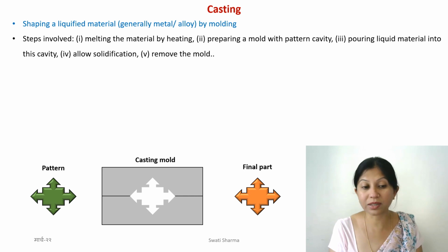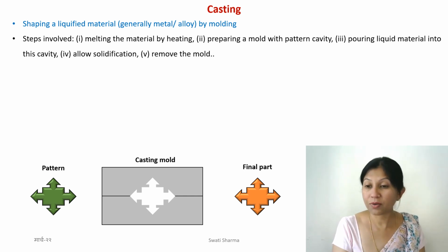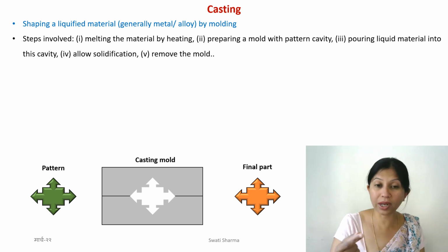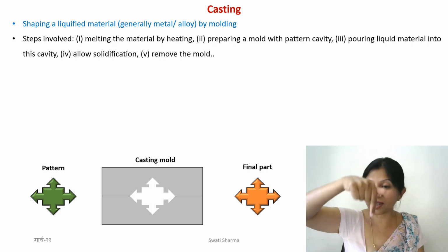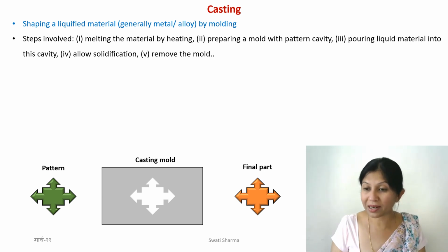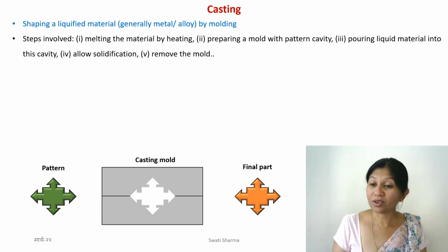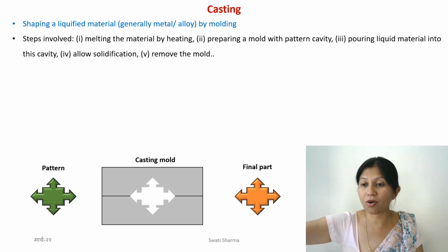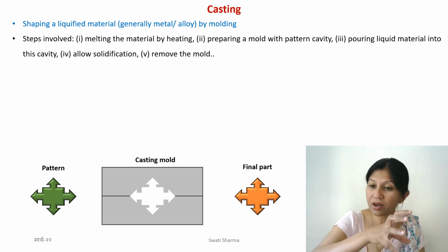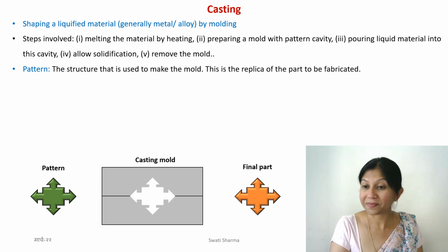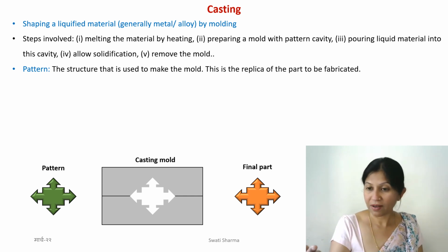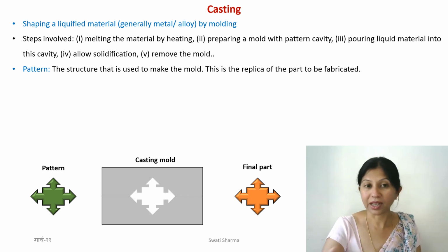One problem all of you must have noticed is, how do we pour the metal? Pouring the metal requires some sort of channel, right? There should be some cavity, some channel through which you can pour the metal. Also there can be some other channels where the displaced air or displaced material can go. So there should also be some cavity on the other side. Otherwise you will never be able to pour the metal. So this basically is an incomplete design. Fine, we are going to learn about the complete design in the next couple of slides.